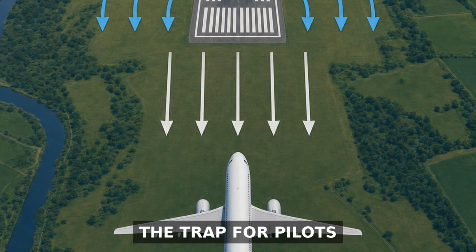Here's the trap. Flying into a microburst on approach, you first meet a sudden headwind. Your airspeed jumps and the aircraft balloons, so you reduce power. Then you hit the core downdraft and the aircraft sinks. Finally, a tailwind steals your airspeed just when you're low and slow.